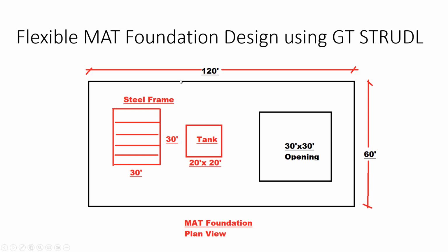So in the end, this type of concrete foundation needs to be designed for all these loadings and openings and stress concentrations that are going to be caused due to these openings and the loadings applied to the mat. It is sometimes very challenging, but at the end of the day, what we're trying to do is approximate the behavior of this flexible mat foundation using finite element analysis. So things are not going to be super accurate or exact.